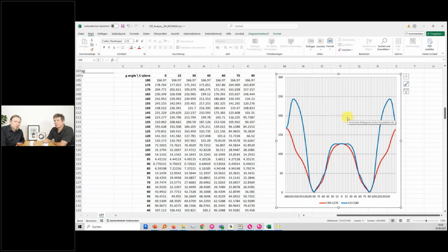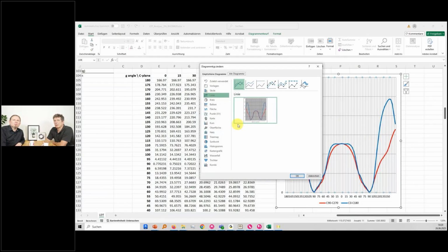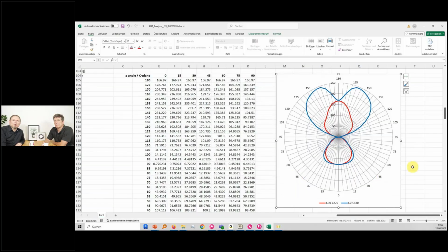This Cartesian is also still in Relux Desktop. It's a property of the LDC. You can switch to Cartesian coordinate systems, but I'm jumping back to polar because this is more used today. You can also change the planes here if you like, so from 0 to 15 to 30, and then you have here at least a half of it changed, or here both 90, then you have both 90.